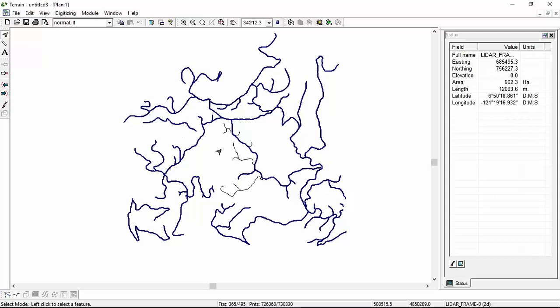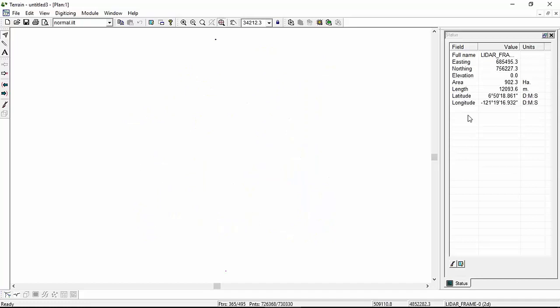Right away, I can see that there's no new points here. Let's zoom extents. Oops. We've got a tiny dot at the top of the screen, and we've got the current point way down at the bottom of the screen. Let's see what's down there. This is a classic coordinate mistake. What we've got now is the LiDAR data down here at a completely wrong location compared with my road data.